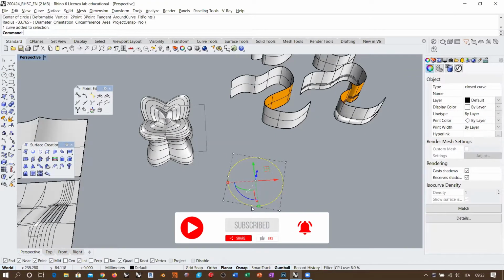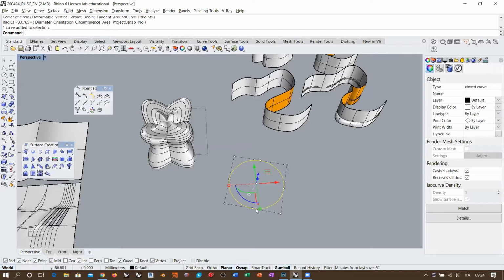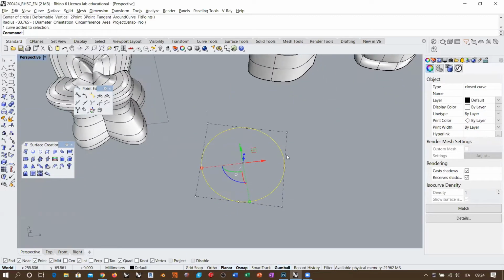You see that here we have these control points that lie on the surface, and we saw that when we have control points that lie on the surface, these are most likely kinks or knots with full multiplicity. In this case, if we analyze the knot vector of a circle, these knot values would appear twice inside the knot vector because this curve has degree 2. Okay, so full multiplicity for a degree 2 curve means that the knot value appears twice.